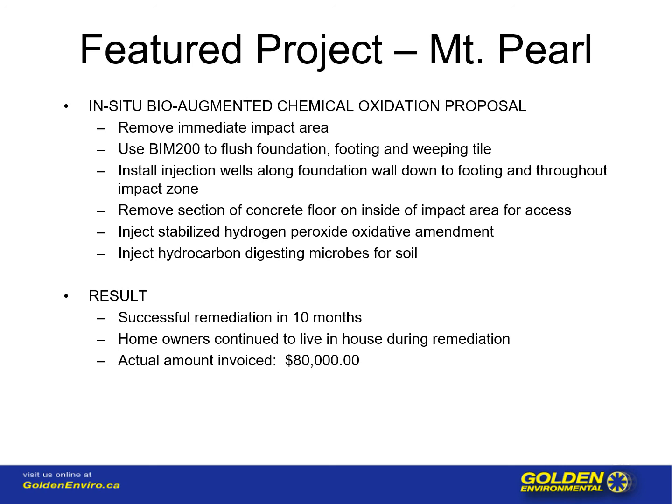Then we installed injection wells along the foundation of the wall down to the footing and throughout the impact zone.